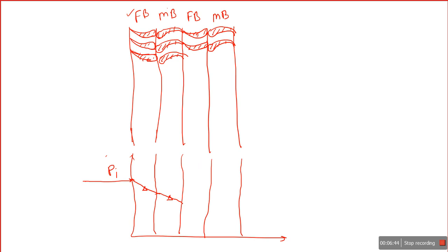Now again the steam flows over the fixed blade, it acts again as a nozzle. We know the function of a nozzle, there is a drop in pressure, correct? When the steam again flows to the last set of fixed and moving blades, there is again a varying cross section, there is again a drop in pressure, and that is the outlet pressure.